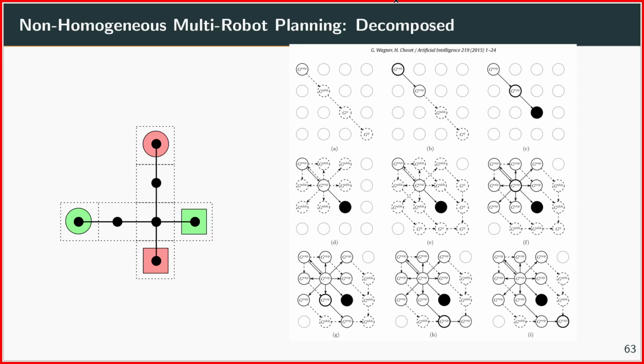So in the first step, you execute the first step, which means you move both robots here one step down along the shortest path. Nothing happens, no collisions, so you just continue until you come here to the third picture where you have actually a collision, because now green and red are both here at the intersection. And now you have to somehow backtrack, and M star does it in the following way.